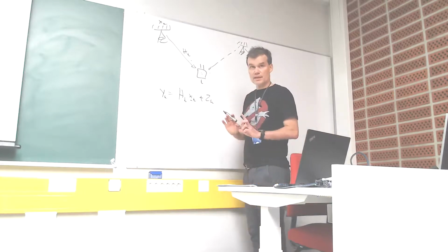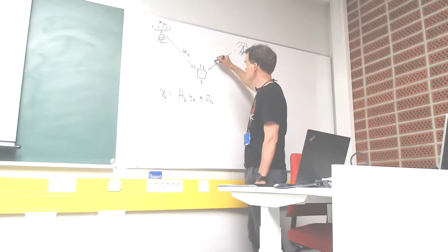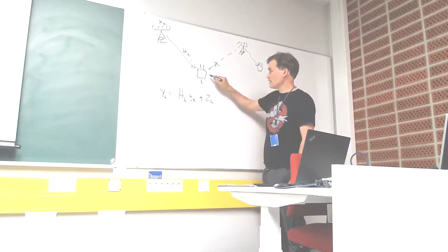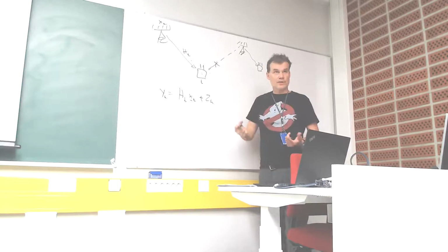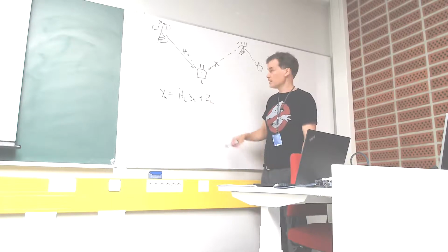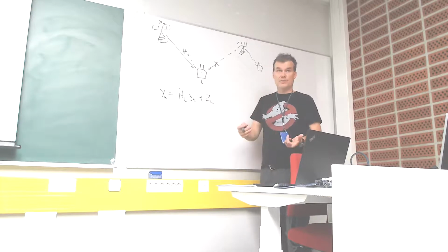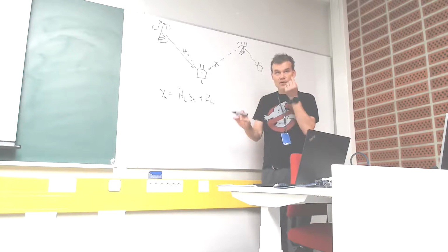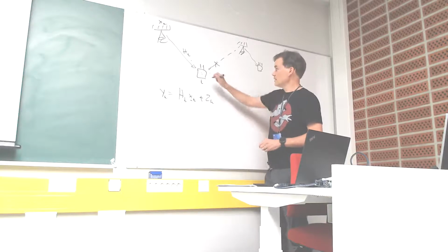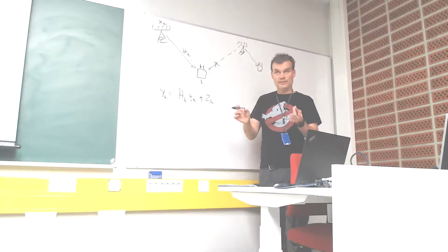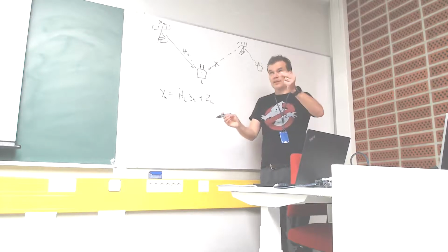But it's not necessarily white any more, right? If this link was not there, then the noise would just consist of the thermal noise introduced by the RF at the receiver, right? And that we can assume to be Gaussian distributed and uncorrelated over antennas, right? That's why it's called white. White means uncorrelated. So the noise process in each antenna is independent, not correlated. That's why the covariance matrix becomes diagonal, right?